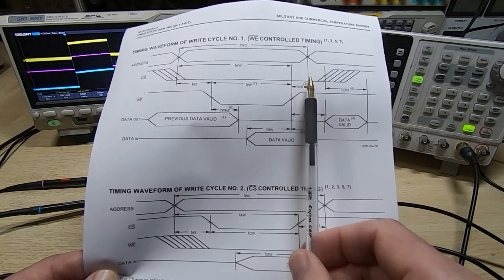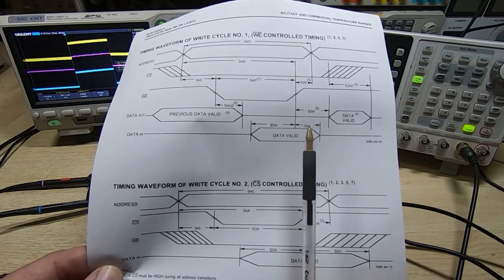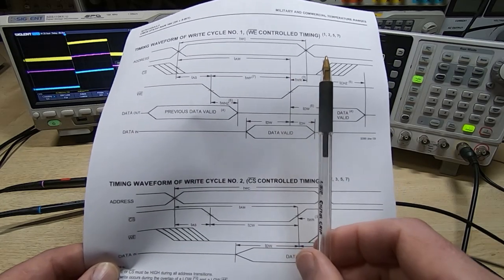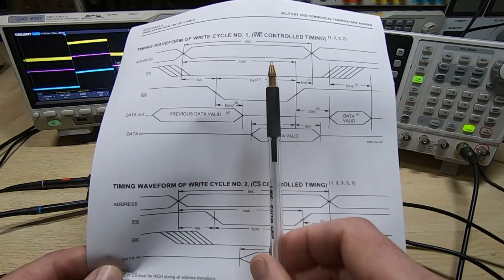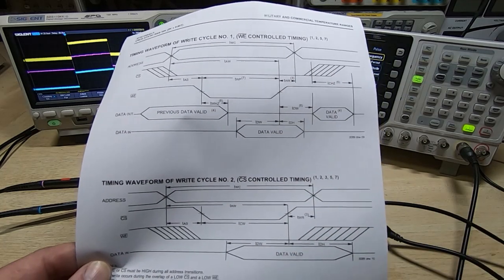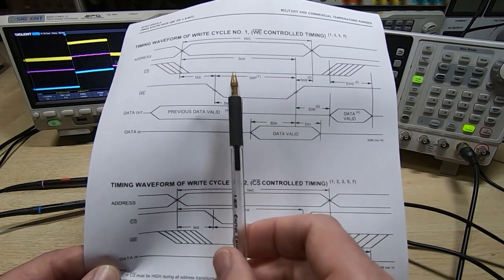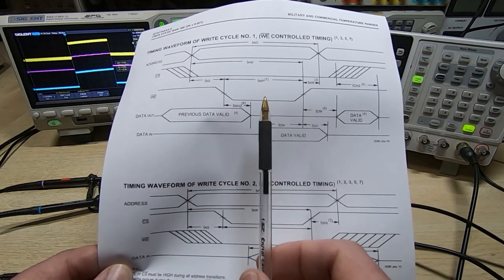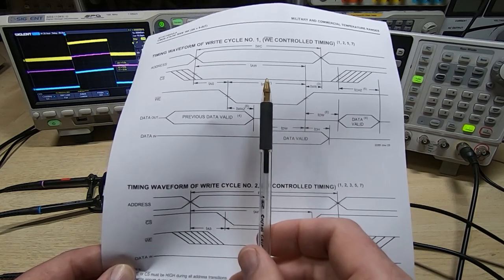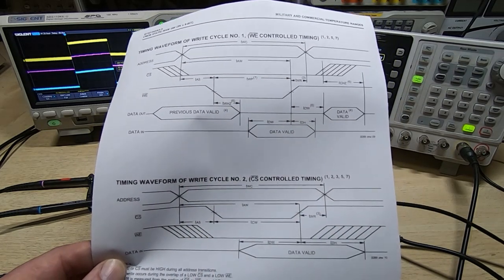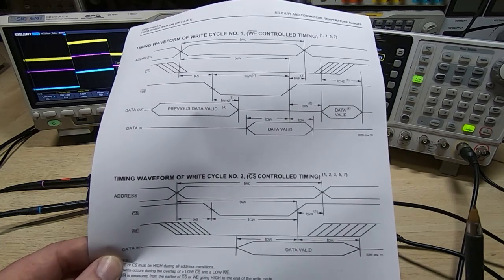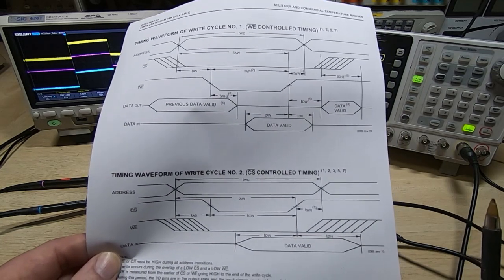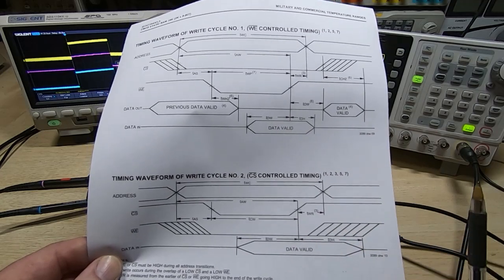And that's what causes it. It's when these edges occur at the wrong time. It's not because there's a race condition, it's simply because the devices are taking too long to do their job. And while the designers did a good job initially, they do expect the devices to operate within a certain window, a certain specification. And when they no longer do that, you can encounter problems.